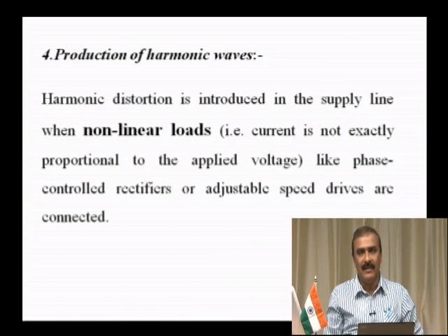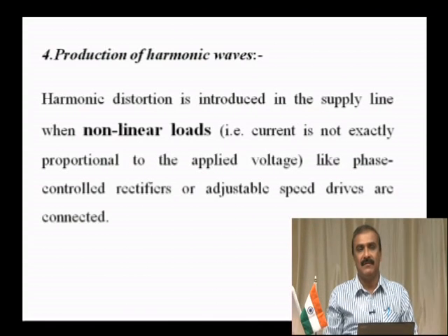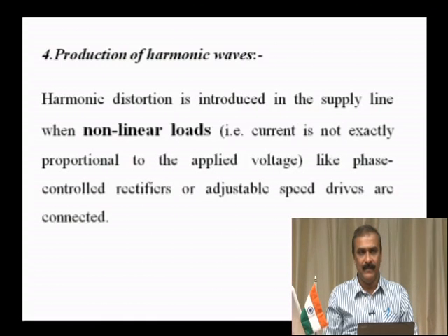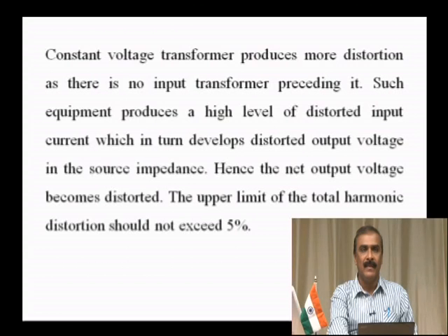Now when we use these kinds of semiconductor devices for speed control of motors, which is quite common in industries, this will cause harmonic production. These introduce non-linearity into the circuit. So we should take care of these drives and switching harmonic waves.